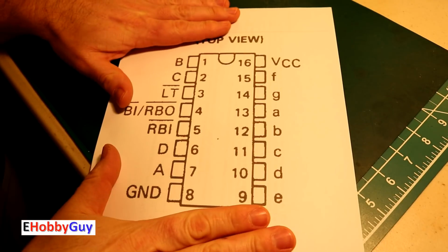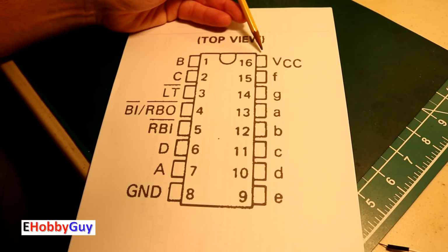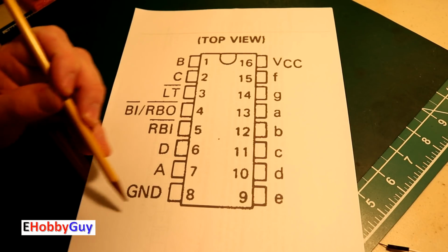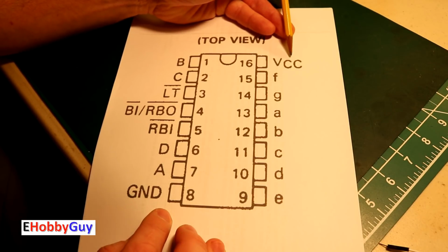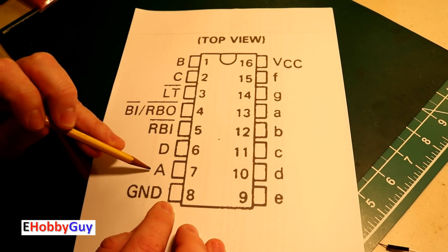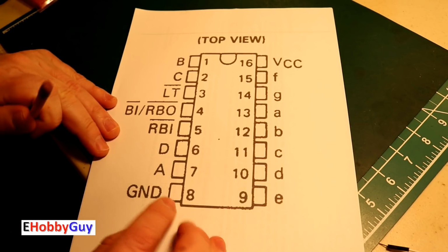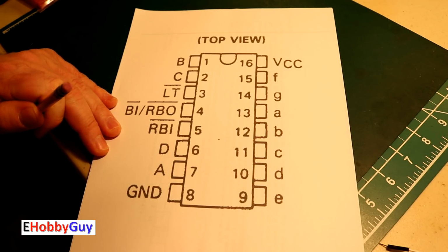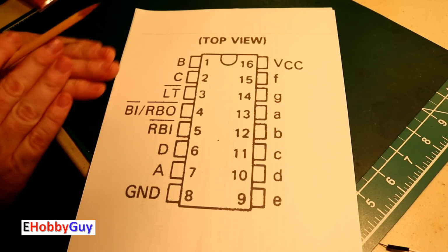Taking a quick review at the chip here, we'll break it down really quickly. On pin 16 here we have VCC, which we're using 5 volts. Pin 8 is ground. So they're the two things that are pretty much a constant with all of these ICs. Now right here on the left side of the chip, we have A, B, C, and D. These are the 4-bit binary input, and we're going to talk about that in a second. We'll talk about these 3 pins, 3, 4, and 5, closer to the end of the video.